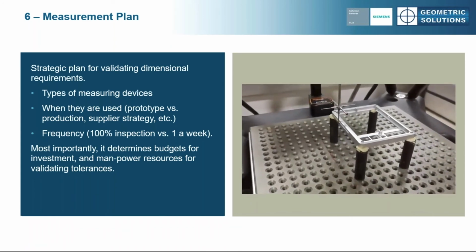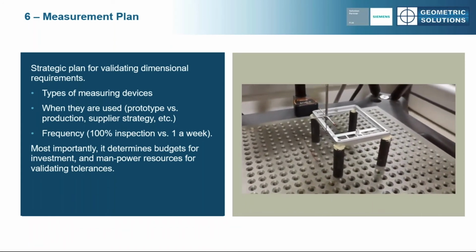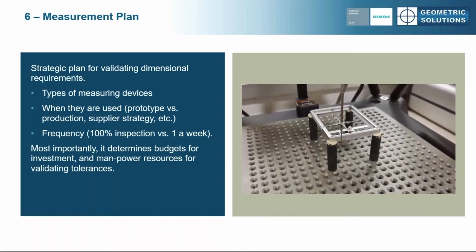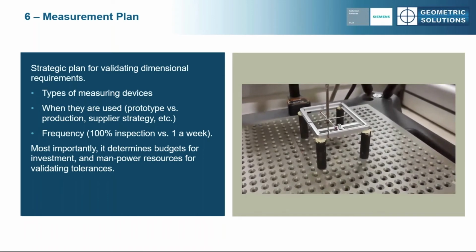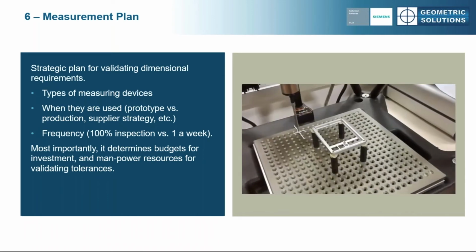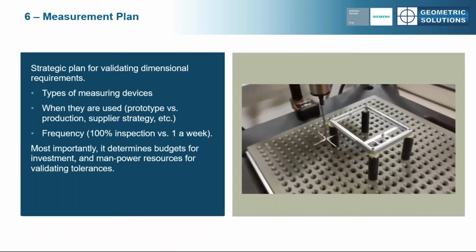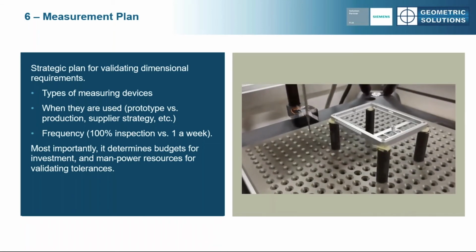A lot of companies, they get down to their final end of it and they start getting their program ready. And oops, we don't have any money for gauges. So they're all going to go through the coordinate measuring machine because I don't need gauges. But then it becomes a bottleneck because it's one machine checking multiple parts and it's one at a time.